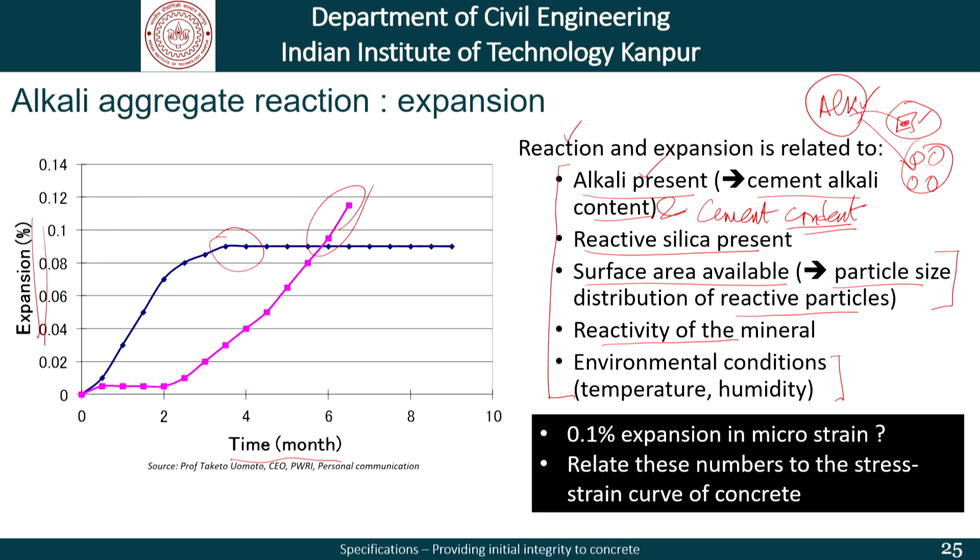I am leaving it to you to find out what is 0.1% expansion in terms of microstrains, because some of us are more trained to think in terms of microstrains and try to relate that number with the stress strain curve of concrete or steel, and then you will realize what is the import of something like 0.1% expansion on account of alkali aggregate reaction.